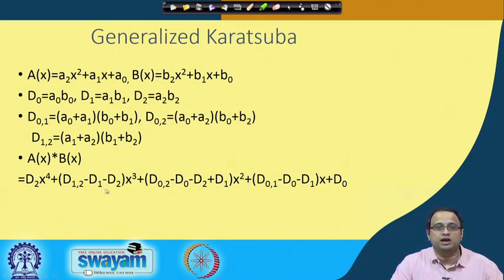The interesting part is that when you have decompositions of this form, each of these terms has 3 arguments or 4 arguments. Okay. So, if you remember the old discussions that we had on the lookup table structure for the FPGA, it already has fixed inputs. That means if you are not using all 4 inputs, for example in a 4 input lookup table, then you are underutilizing the lookup table. Okay. And that is why general Karatsuba seems to utilize the lookup tables better, because it always has this number of input arguments for each of these terms. Okay. So, you get a better utilization in the general Karatsuba, but as I say, when you implement a general Karatsuba, the gate count increases. So, for higher dimensions it is not a good choice, but for lower dimensions it is a good choice.